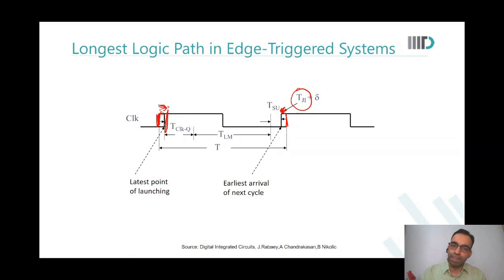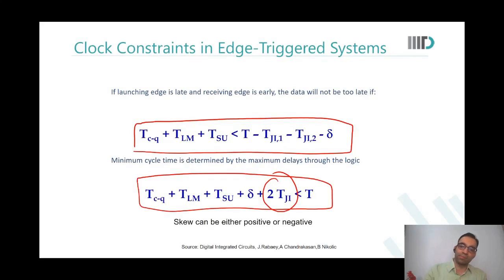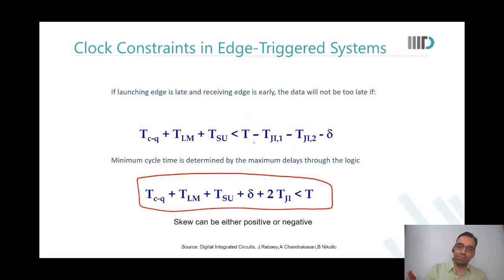But when you were explaining jitter, you were saying that in the same flop, how it is arriving. We were not considering 2 different flops. So for two different flops also there will be jitter, na? Yes. So in the skew constraint equation, I will subtract this 2 times the jitter. I will add this jitter also twice. No, it's the same equation. We just moved the negative terms from here to here. That's it. So this is for the setup.